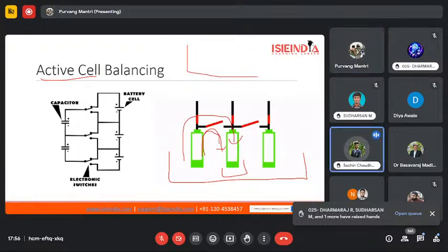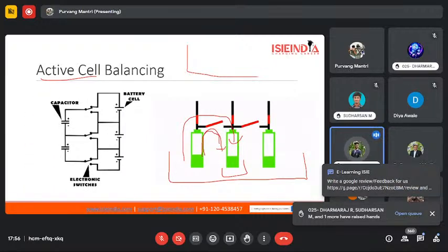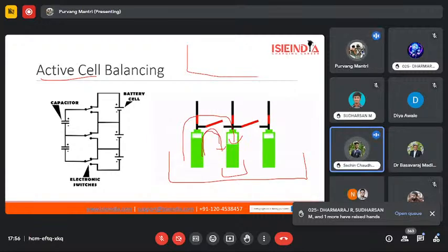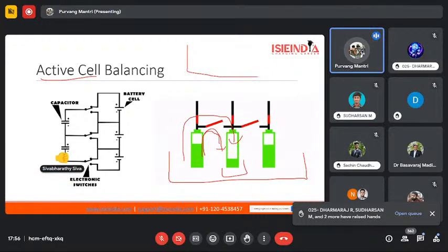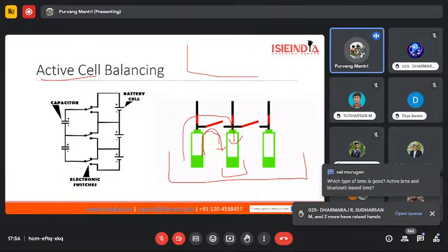Is it a battery management system problem or a cell problem? Cell problem. Why does the battery management system first show the reading 100%, 89%, and then suddenly decrease? Because it is monitoring the voltage, it will see that the voltage is being depleted from one cell or a number of cells pretty easily. So that's why the number that it is showcasing on the screen would drop down pretty quickly.